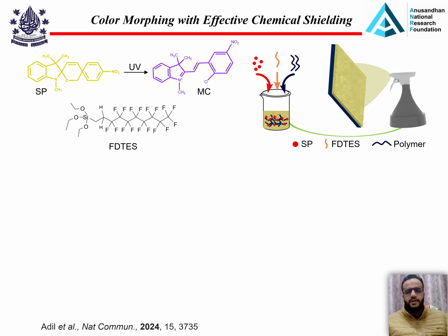In addition to the slippery liquid surfaces, as I mentioned, superhydrophobic surfaces are not repellent to different organic liquids. However, slippery surfaces can overcome some of the limitations of superhydrophobic surfaces, but they are also dependent on the lubricant which is infused in the surface. If we infuse a hydrocarbon lubricant, it won't be able to repel organic liquids like organic solvents. So in order to repel a variety of liquids, another concept in the literature is called super omniphobic. Super omniphobic surfaces are those surfaces which can repel both water as well as oils.